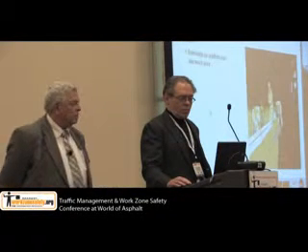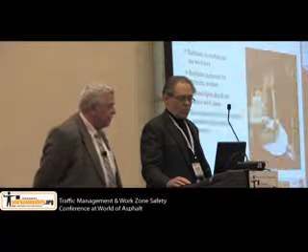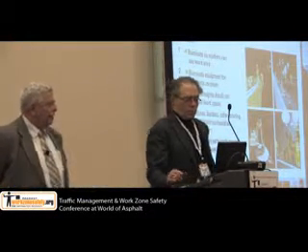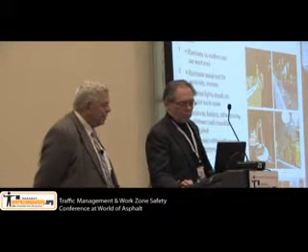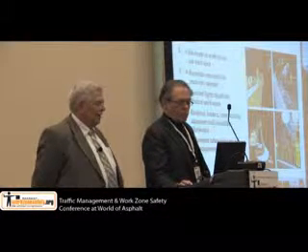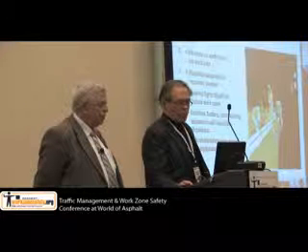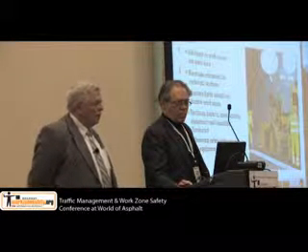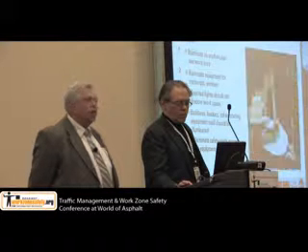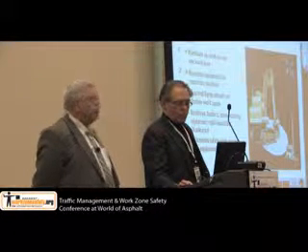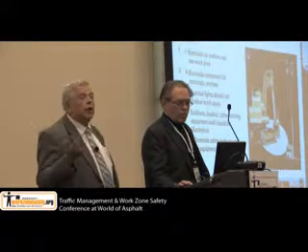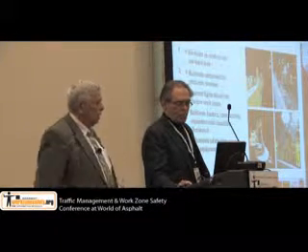What should be illuminated? Obviously, so the workers can see the work area, the motorists can see the workers, the mounted lights not put you in shadows, the backhoes, buckets, other equipment not only should be illuminated, but the illumination should be around the safety circle around the equipment. So that you can see it.